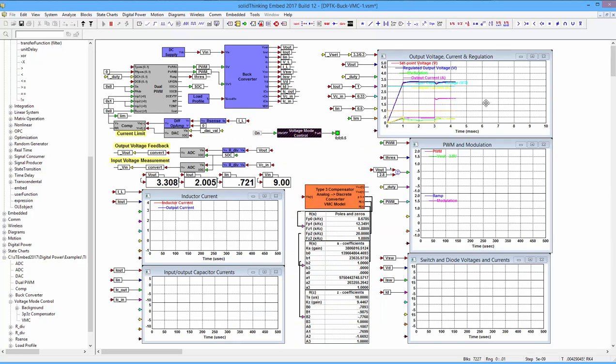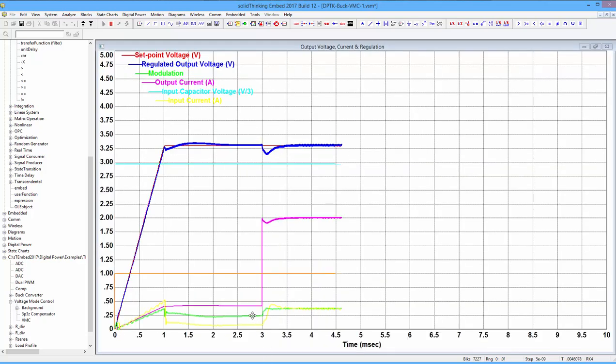Okay, so now we're doing a simulation of this. We had a load step here, which is emulating the step of the load on the actual TI experimenting kit, which is the workshop kit, the digital power training kit. This is the base load on that kit, and then we have an active load where we can go up to above 2 amps. Here we drop the input voltage in response to the input voltage drop. Again, we'll increase the input voltage shortly.